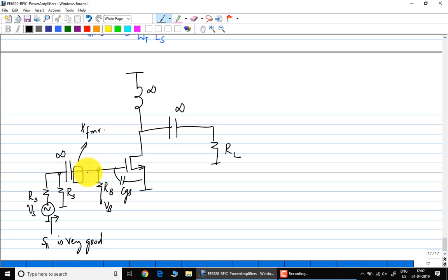Okay. I'll just show that conceptually like this. I'll call it some LB. So if LB has a finite quality factor, you now need to change RS prime such that the overall input is 50 ohms. Understood? So the understanding is that if the inductor is not ideal, the input impedance will change. The input impedance after RS prime may actually be 500 ohms, in which case you can't do 50 ohms, maybe you will need 55 ohms or something.